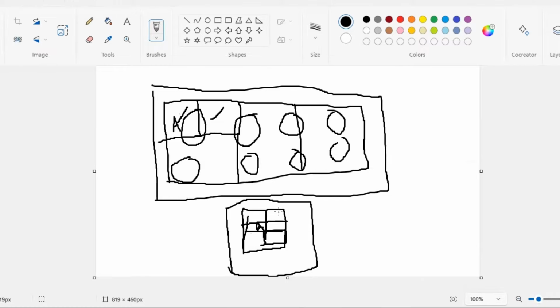In this block there are different types of memories and modules. In modules, there are different types of standard cells. Standard cells are nothing but AND gate, OR gate, XOR gate. These types of gates are known as basic gates, and we know all these things. This is combinational logic, and the flip flops will also be there inside the module. Got it, right?